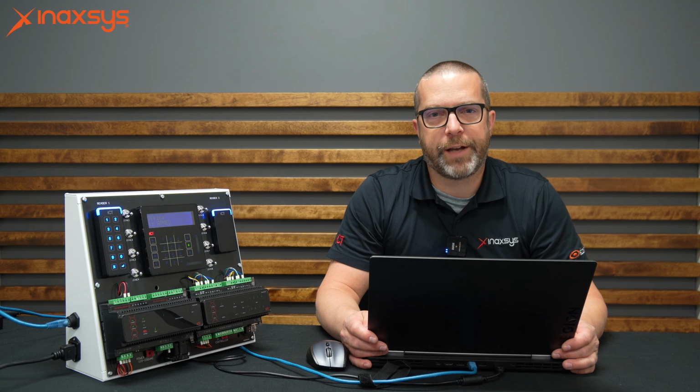So basically the input type will define how the input works and what it does. Let's say there's delay, instant for intrusion alarms, but now I'm just going to create a dummy area and a dummy input type to enable the zone and make it so the zone will activate the output. Okay, so we need to have the zone in an armed partition for the output to trigger. Okay, so first step, under input types, we created one called door chime. Okay, very simple, nothing fancy there.